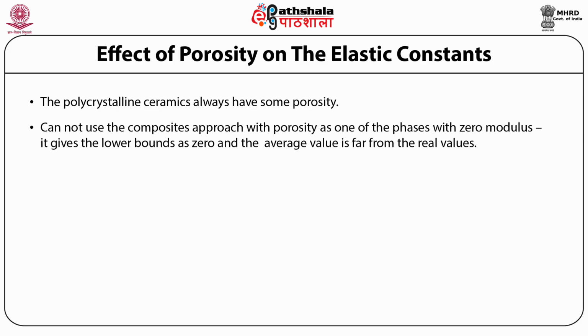It is not fruitful to use the simple composites approach with porosity as one of the phases with zero modulus, because now the lower bound is 0 and the average value is far from the real value. So some approximate relations are available for this case.